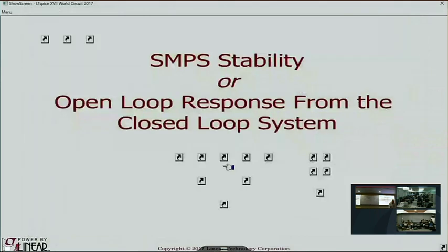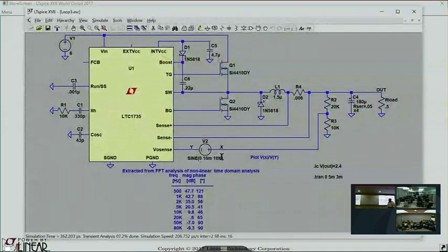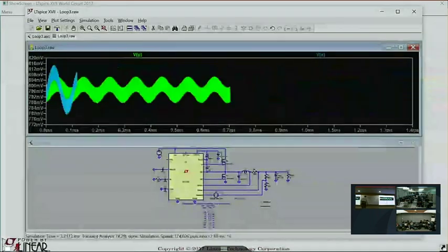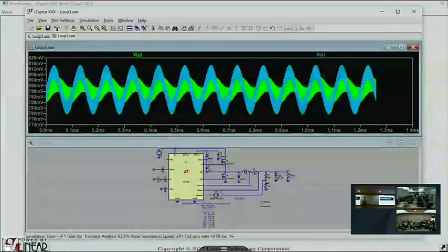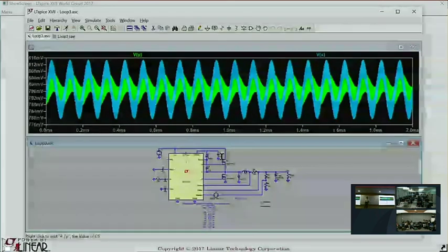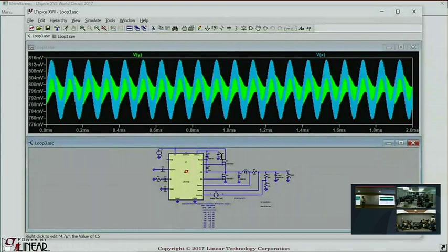Now, in a switchable power supply, the problem is even worse. This circuit does not have a linear frequency domain analysis. There's no frequency domain description of this circuit. Again, frequency domain analysis works for a linear system. If you have a linear system, all the frequencies are orthogonal. You can solve for the circuit one frequency at a time, and that is a correct way of looking at it. You can do that with correctness in a linear system. If you have a nonlinear system, then the frequencies are not orthogonal. They mix, and you can't solve it one frequency at a time.